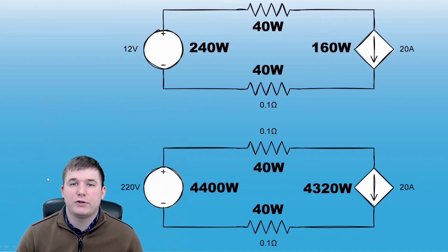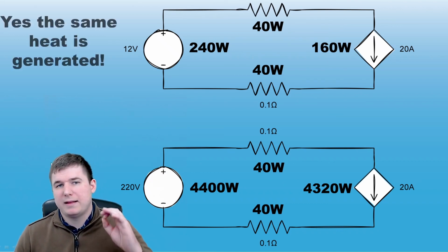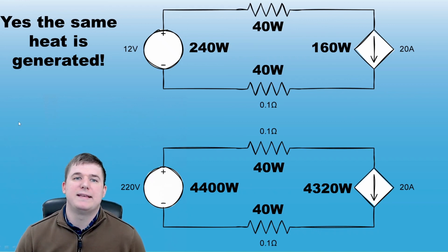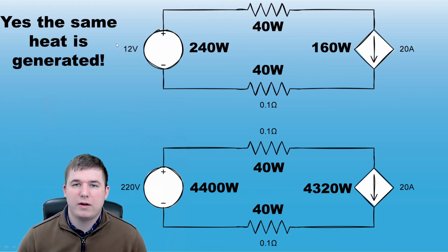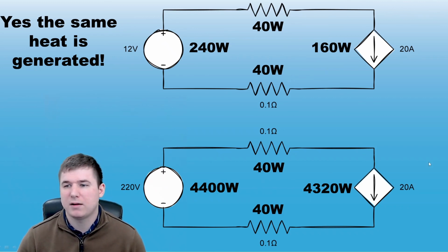So what's the conclusion from this? The answer to the question is yes. The same heat is generated whether the wires are being energized to 12 volts or 220 volts. It all is dependent on the current flow through the conductor, through the wire.